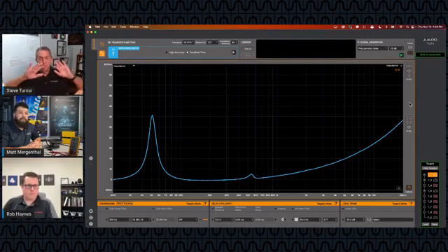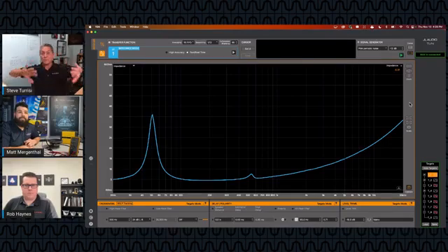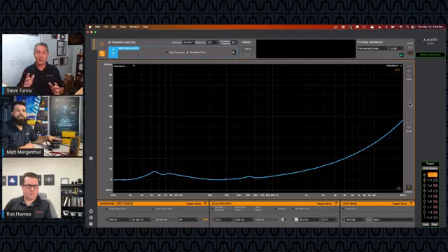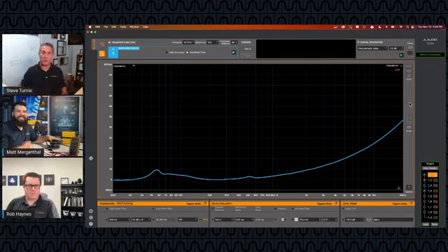But yeah, for sure. If it was hitting the speaker and you didn't push it, the impedance would look pretty stable like it is right now, right? So if Matt could rest his hand or take a pen or something and leave it on the piston, it will stabilize and show an impedance measurement. You don't know if that's good or bad, right or wrong, it's the change that happens when you push on the door panel, by seeing it fluctuate the way his measurement was a moment ago. That's how you know that there's something that you should probably address.